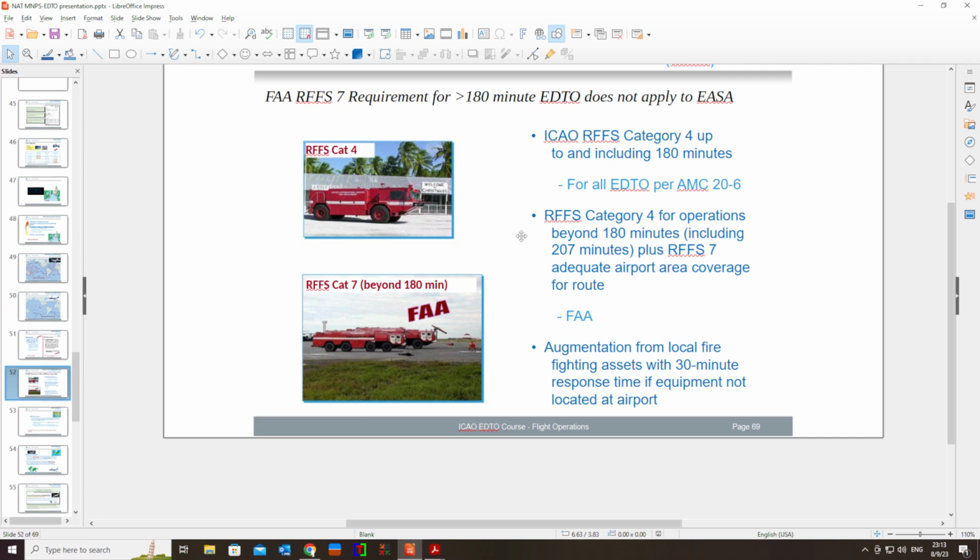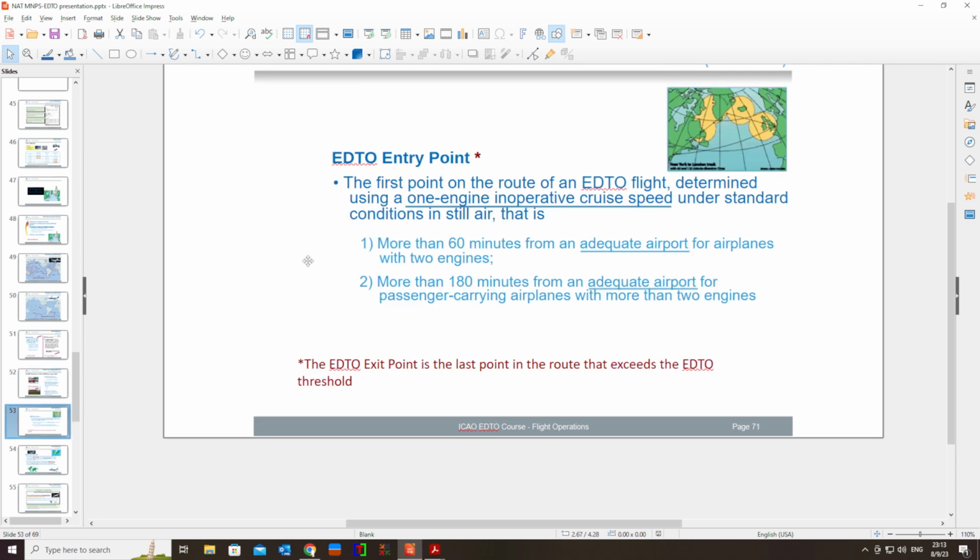With the A321neo, we can go down to 5 with a special approval from the authorities where the aircraft is registered. 6 is okay, but we cannot go below 5. If 5 is the minimum, I would say 6, 7, and above. So we need to pay attention to that too.